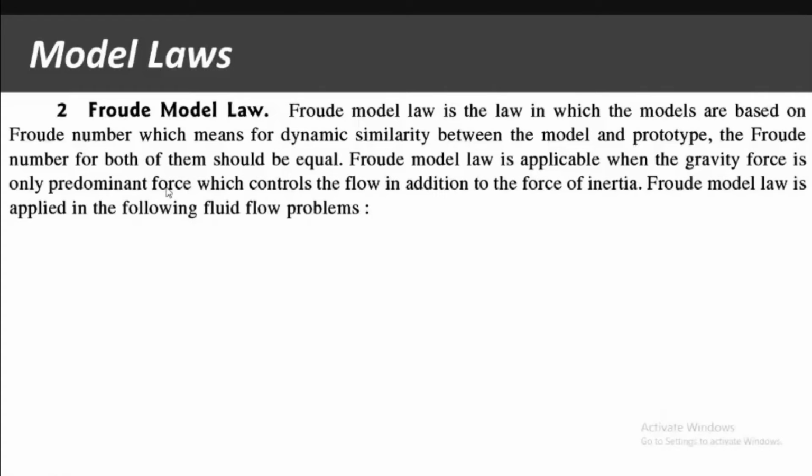For example, flow through a waterfall. In Marathi we call it झरना. Basically what is happening in a waterfall is that water is falling from a particular height, so all the flow of the water is completely controlled by gravity. Suppose you want to install a turbine in that waterfall. In that case, whatever the input energy, the kinetic energy, is governed by gravity. So whatever the energy of the fluid, the hydraulic energy, it will be governed by gravity. So in such types of models, the Froude model law plays a very important role.